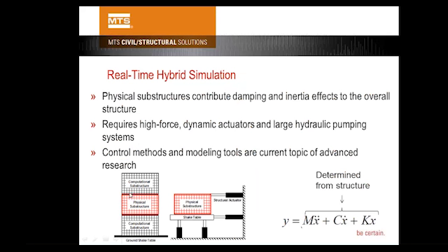So the response of this structure is very dependent upon the rate. And the earthquake has to be real time. The test has to be real time, same scale as the earthquake. Otherwise, the inertial term will not be right, and then the response of the structure will not be right. So in this kind of case, the hybrid simulation has to be real time.